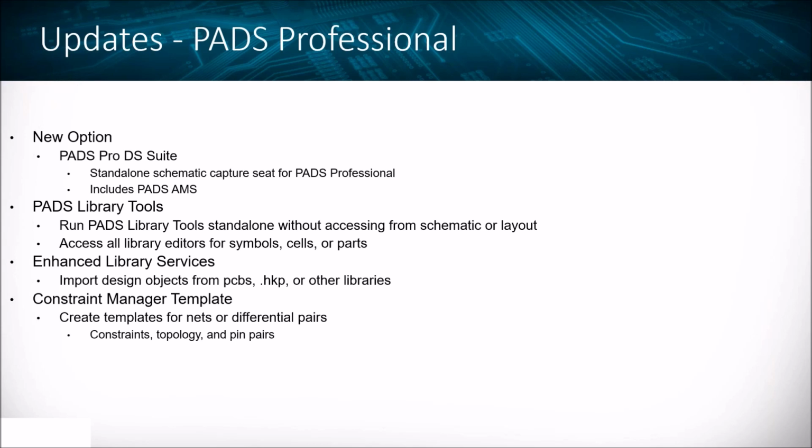What that does is allow us to do SPICE simulation directly in the schematic without having to redraw it in an LTspice tool or anything like that. We can do all of our SPICE simulation directly within DxDesigner, ensure that the circuit works correctly for us, and then forward that directly onto the layout. Okay, so it can be a very powerful solution.